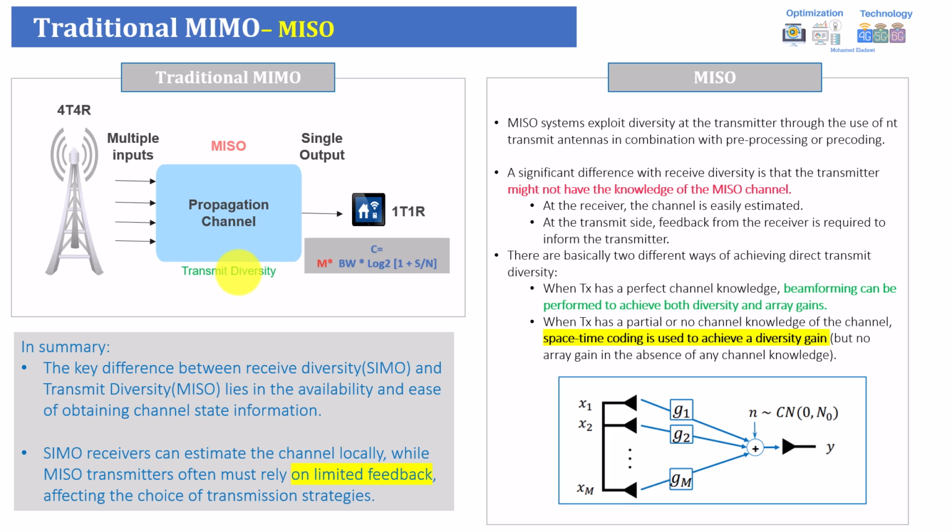The first one asks for channel knowledge, which is through feedback. It will ask the UE to give feedback about the channel knowledge. Once the UE feeds back the channel knowledge through PMI, for example, it will tell the transmitter: this is my CQI, this is my PMI, this is my rank. So the transmitter will understand fully the current channel condition and know all the information about the user. In this case, you can utilize the multiple antennas to achieve transmit diversity or array gain.